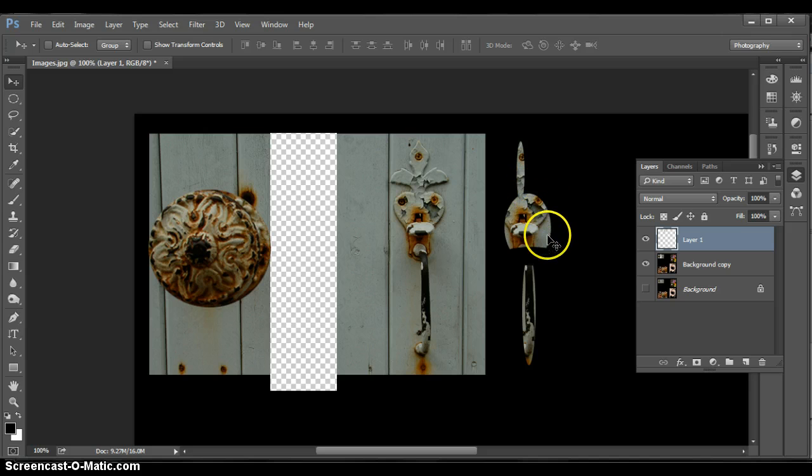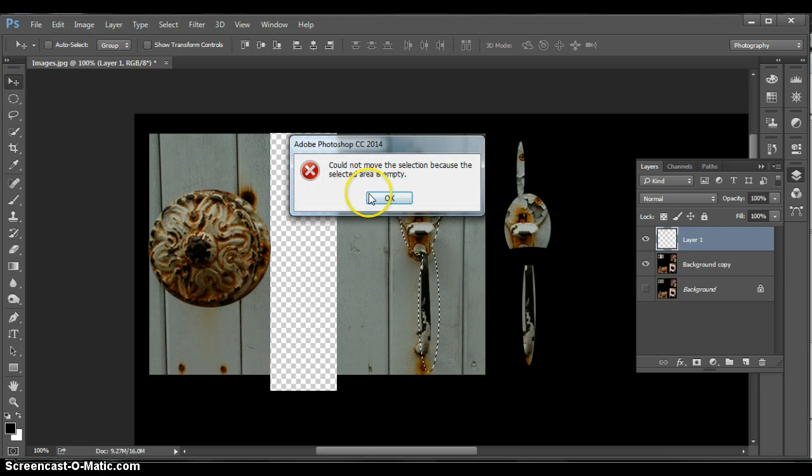But what I wanted to show you, the difference here, is that notice with this selection I have a pretty crisp edge to it. If I come over here and I set a feather, let's say of about 3 pixels, and I'm going to go ahead and get about the same sort of shape here from the other one. And let's say I move these.